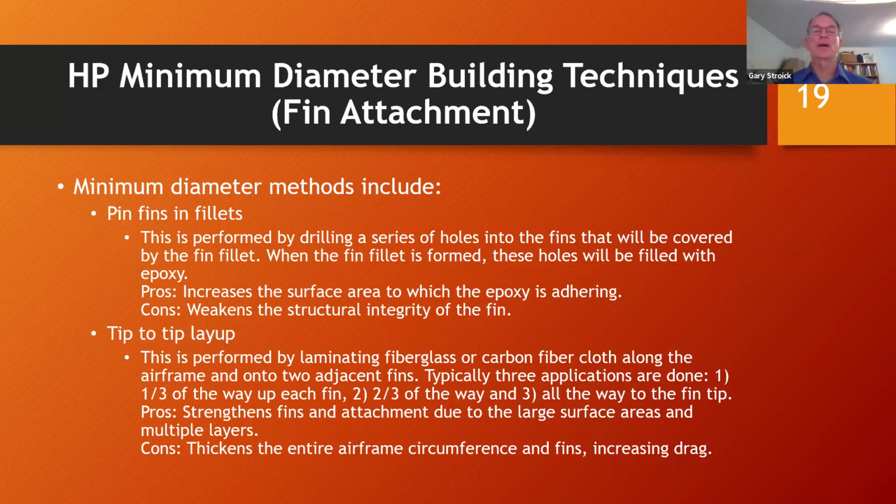Gary, can I ask for a clarification? When you talk about drilling holes, I haven't done this myself. Are you drilling holes sideways through the fin from one surface to the opposite surface, or are you drilling up into the root, into the fin? Thank you. I will make the clarification. Yes, it's from one side of the fin to the other. So it's across the width of the fin material. If you have a 1/4 inch fin material, it's from one side of that 1/4 inch material to the other along the root cord.